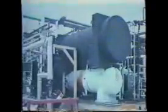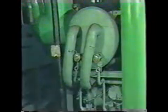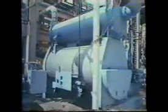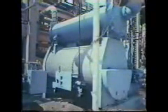In the example that we've just seen, a direct expansion evaporator was used to cool air. But other direct expansion evaporators may cool water or some other liquid. Evaporators that cool water or other liquid may also be called chillers. You should be familiar with both air and water-cooled types of evaporators, as you'll probably be working with them both at some point. Another type of evaporator that chills water or liquid is the flooded evaporator, also called a flooded chiller. They are often used to provide chilled water for air conditioning systems.